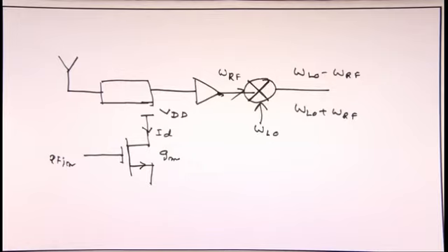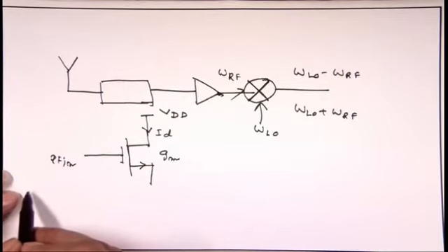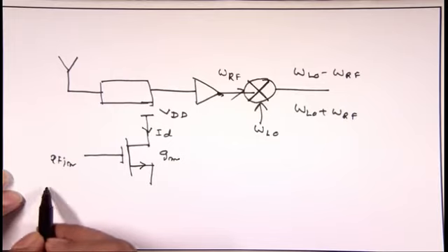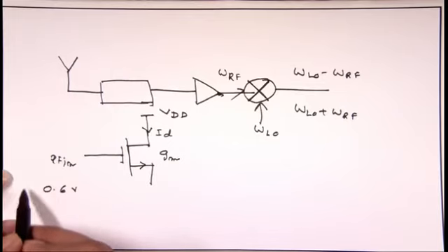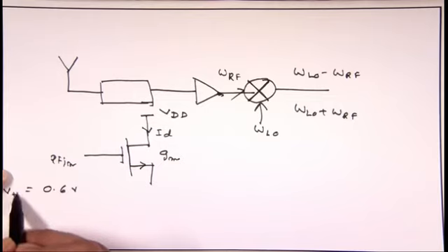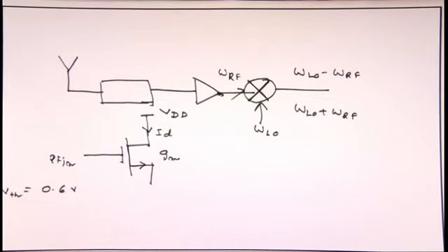So, if you make the RF in, for example, 0.6 volt is my threshold voltage, right? And normally RF is pretty low, means it is not, say, 1 millivolt peak to peak or 100 microvolt, because it is after the LNA, you are giving a gain of 16 dB. So, typically you are expecting 0.1 like that, 100 microvolt, 200 microvolt like this.